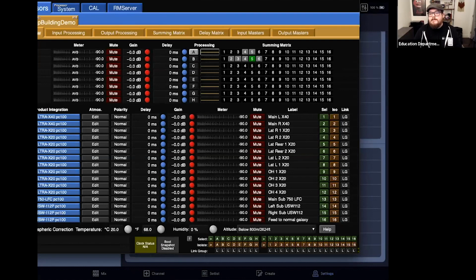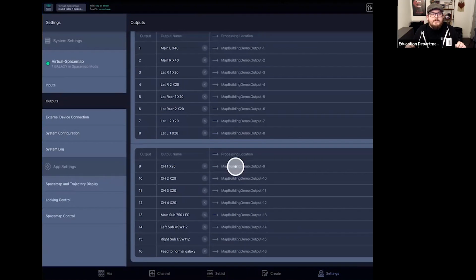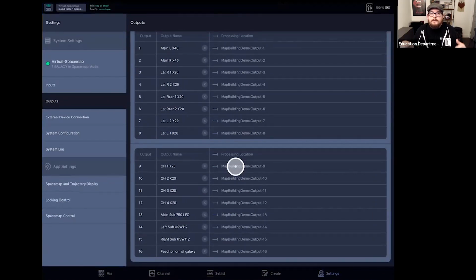In terms of input signals, can AVB and analog inputs be used simultaneously in a single galaxy? For instance, 8 analog inputs and some AVB inputs? Yes. So one important note about AVB is Galaxy is certified to work with Milan certified AVB. There are a lot of AVB products out there that are not actually Milan certified. Things that are Milan certified, you can go to the avnu.org website, and there's a list of certified devices that can interconnect with the Galaxy.